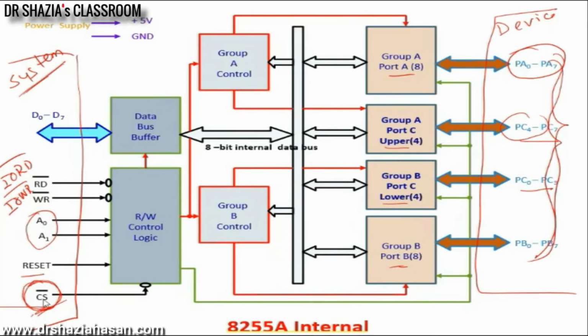That is done through this chip select line. That means before this chip select line, I have a decoder. The decoder is connected to the address lines from the microprocessor, and the decoder output goes low only if the address is among any of these addresses. Hope it is clear.